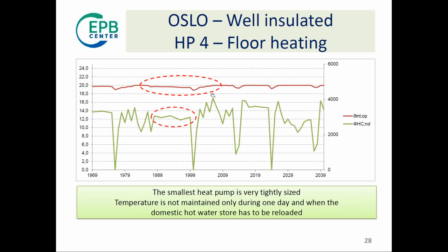And if you go into details, for the worst case, this is the worst day which you could find, so the coldest day, and you see that really here the heat pump was not matching the load, and you lose 1 degree for 1 hour, and that's when you have the reload of the storage. Here the available heat is 0 because we are loading the store, and here you have some difficulty in recovery, but here you are again at 20 degrees. So that's what happens if you dare to use the smallest heat pump.